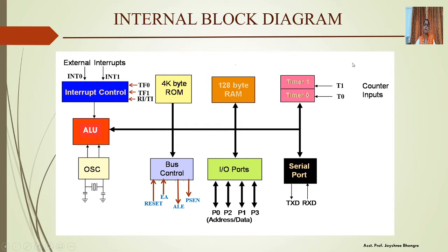Then 8051 has two 16-bit timers, timer 1 and timer 0. They are used to count the clock pulses of the CPU. These two timers are also used as counter inputs to count the external pulses. They are connected to pin T1 and T0.